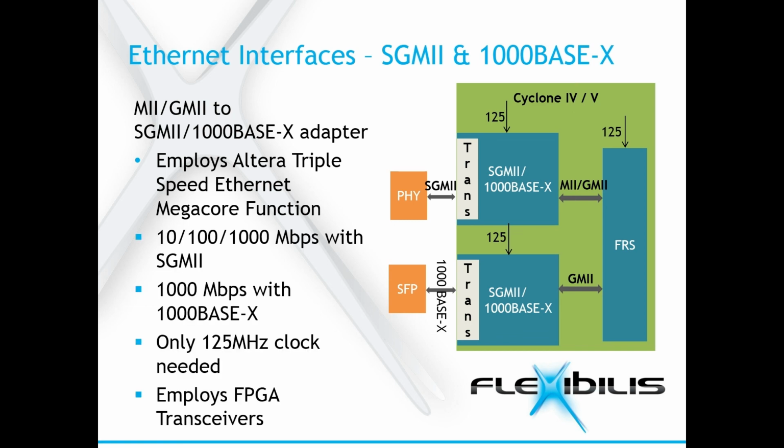Note that the Cyclone V FPGA has a feature that reserves at least one extra transceiver channel to create the transmit clock. Because of this, that one channel can't be used as a transceiver for SGMII, 1000 base X, or 100 base FX. A trial compilation is much recommended before, for example, designing the PCB layout. Cyclone IV doesn't have this sort of limitation.